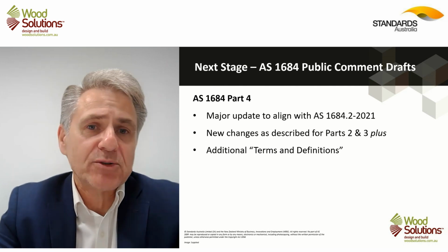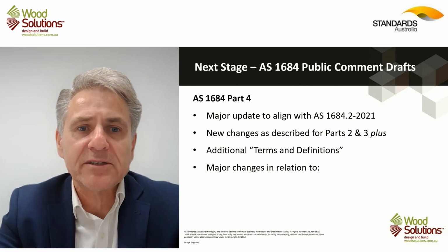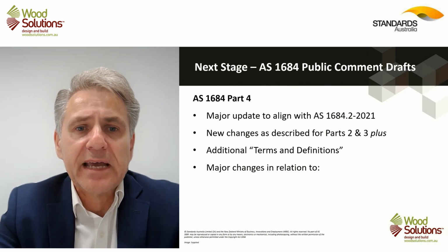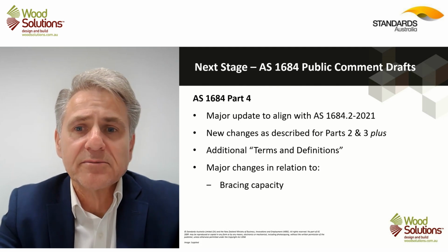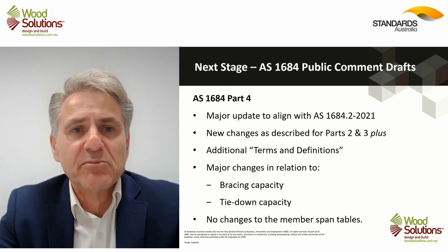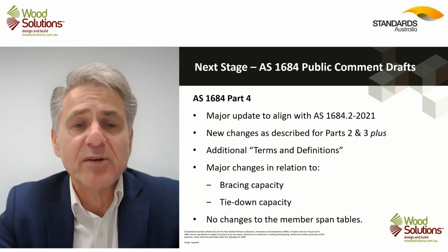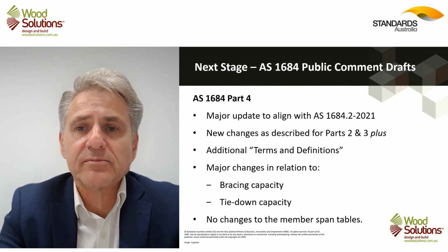There will also be some additional terms and definitions that are introduced in alignment with Part 2. And the major changes, as I mentioned, are brace capacities and also tie-down capacities, but there'll be no changes to the member span tables that are contained within AS 1684 Part 4.